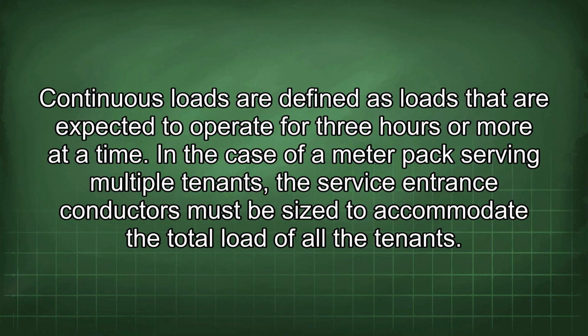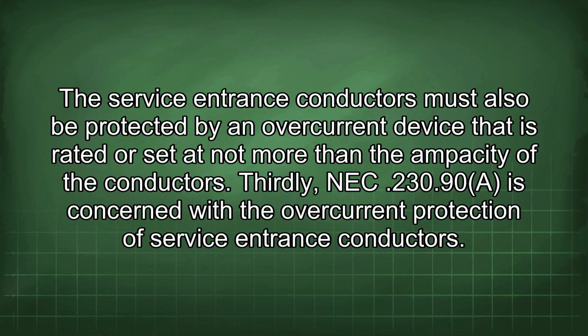Continuous loads are defined as loads that are expected to operate for 3 hours or more at a time. In the case of a meter pack serving multiple tenants, the service entrance conductors must be sized to accommodate the total load of all the tenants. The service entrance conductors must also be protected by an overcurrent device that is rated or set at not more than the ampacity of the conductors.